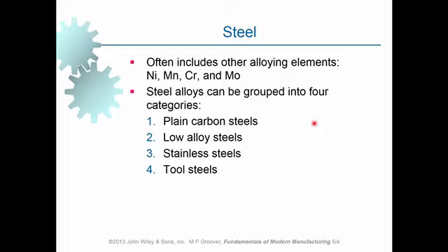They are resistant to oxidation and corrosion. And why is this? Someone said something here. Chromium. How much chromium do we have in stainless steels? I think it varies. How much? Who is talking? Okay. I'm not actually 100% certain. I think it's under 1%. But at least 11%. Yes, correct. Thank you. At least 11% of chromium can be found in stainless steels. Could be more, 15% or even more.